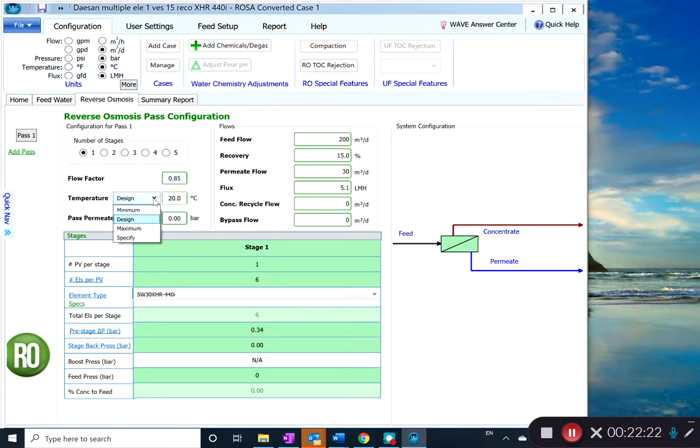And temperature, we design for 20 degree, and water flux back pressure. So when you put the back pressure, let's see in this schematic how they change. So we have a back pressure here, to try to balance your water flow and concentrate flow. Sometimes we utilize the permeate back pressure, but this is energy intensive, so I don't recommend utilizing this one. And let's change the flows.